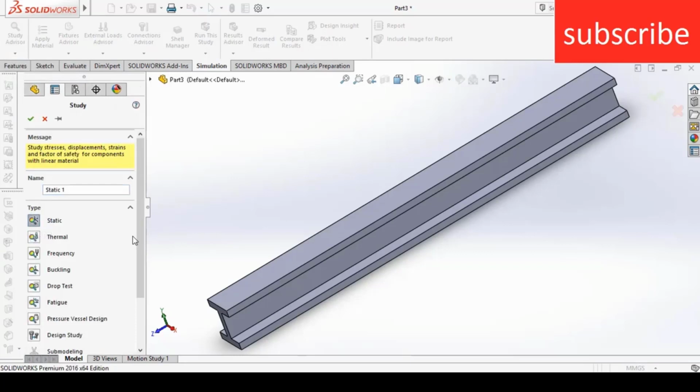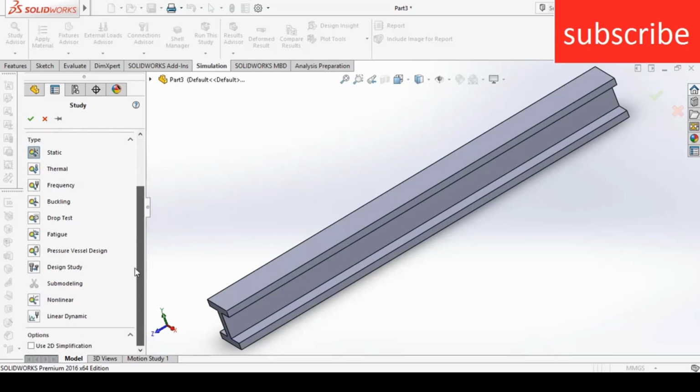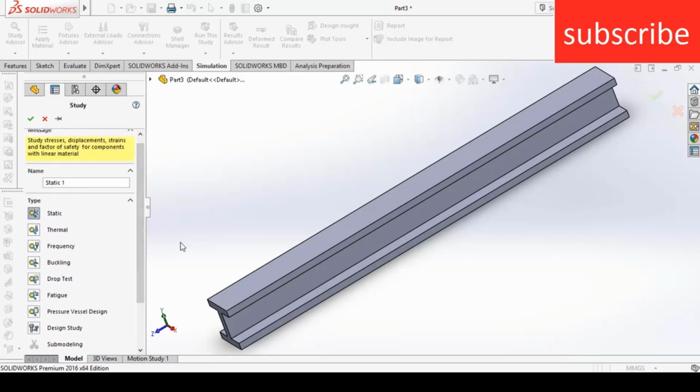A question arises in your mind: where is static simulation used? Static simulation is used when you have a body or chassis or a beam on which a constant load is applied that is not varying with time, that remains constant. At that time you use static load. If your load is varying with time, then you normally use non-linear or linear dynamic. Currently I am assuming that my load is constant and I'm just putting it here as a constant force.